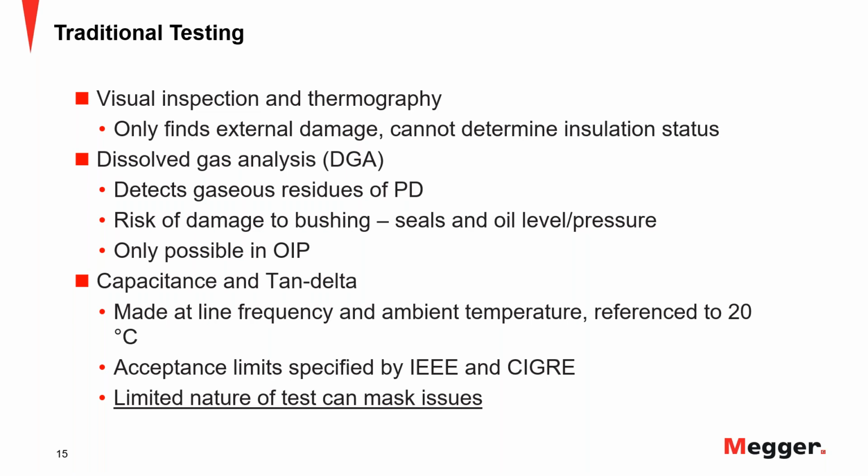Actually, it is recommended to do visual inspections at least once every 6 months, right? Try to be careful, of course, on this, but see what is going around. If there's any leak, probably on the top of the transformer, and on the top of the tank, that may be coming from one of the bushings, try to look if the level of the gauges is okay.